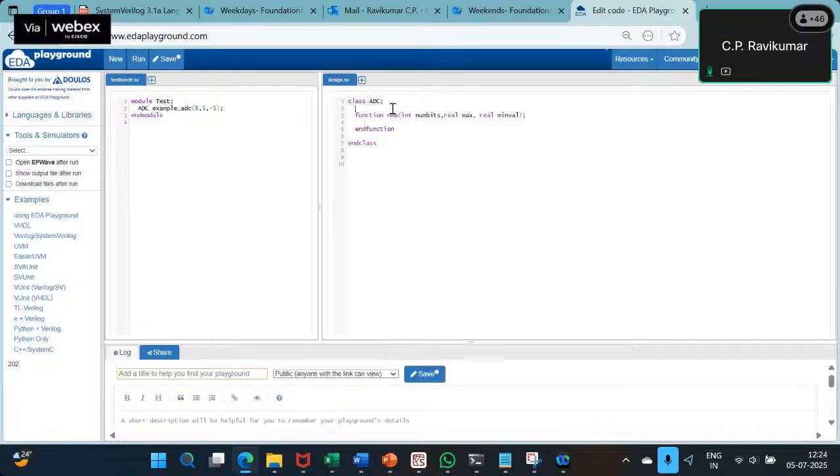So how do I create the register whose bits is num bits? See, if you do something like this, you have to give the maximum. That is one way. You could say the maximum value here I'm going to take is maybe I can go up to 16 or something like that. So this is a successive approximation register. And if somebody says 8-bit, then I will only use the last 8 bits.